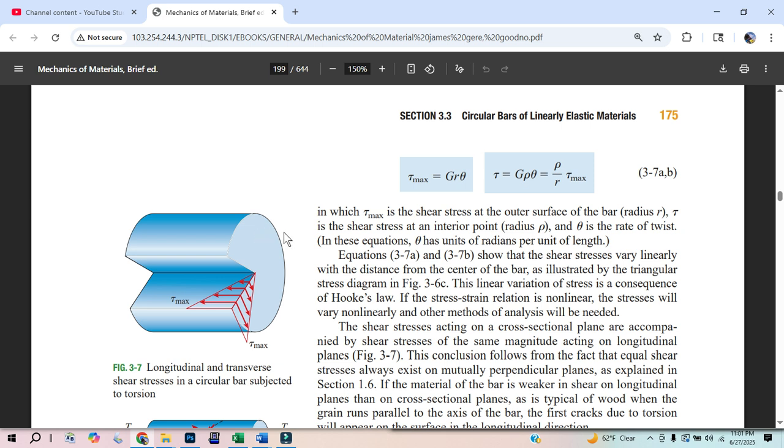And cool. We made our problem really simple: we have a ring of molecules on the outer part, that's what the cylinder is made of. If we have a ring of molecules all the way around, connected to another, and we shear up on these, put little forces, we're going to have little resisting forces on all those other molecules. Those are the shear forces. And if we have a shear force and we know the area, the amount of material that shear force is acting on, then we know this number for shear stress.